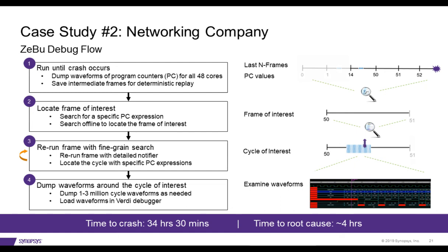After this, based on the analysis, we first found the window of failure. Within that window of failure, we enabled further debug utilities to find an even smaller window of failure. And within that window, we then did the full waveform capture and found the problem.